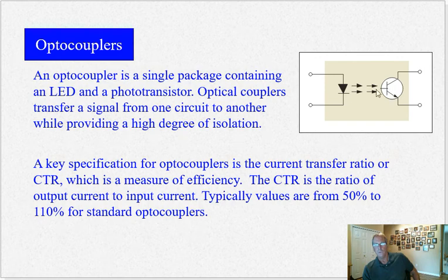And you notice that if you increase the current into the LED, it'll produce higher intensity light, and turn the transistor on more. There's no electrical connection between the input of this device and the output of this device. It's galvanically isolated. And we call current transfer ratio the ratio of the output current to the input current. So the collector emitter current versus the diode current here.